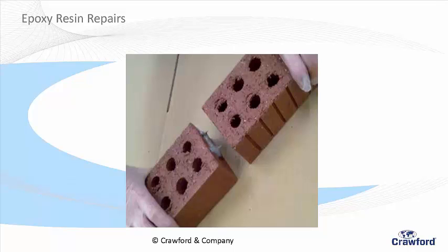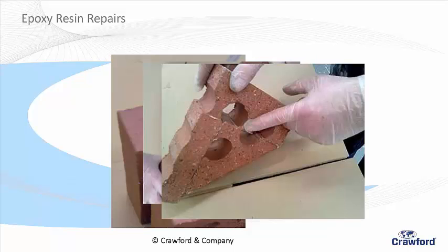Now, when you build a panel of brickwork, they teach you that your mortar has to be marginally weaker than your brick in terms of strength. Do you know why? Exactly. So when you get any movement, thermal or whatever, it's the mortar that cracks, not the brick. If your mortar is too strong, you have too much cement in the mix, it will crack the brick. So you get it crack through, which is not nice, not easy to repair. That is just a disaster.